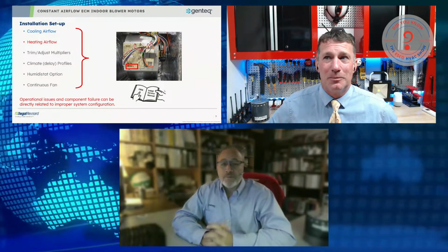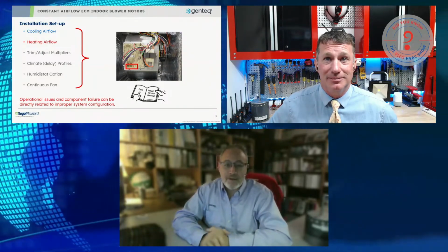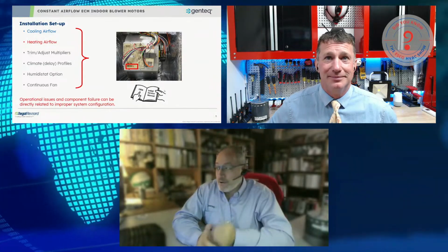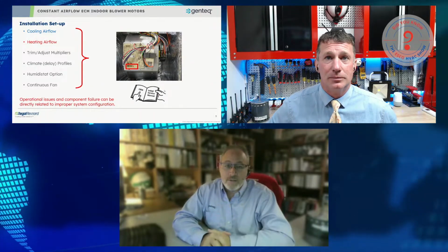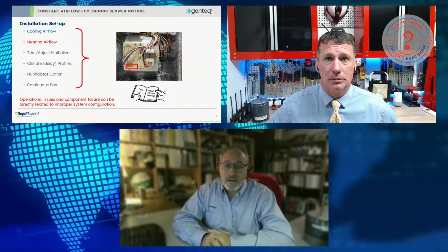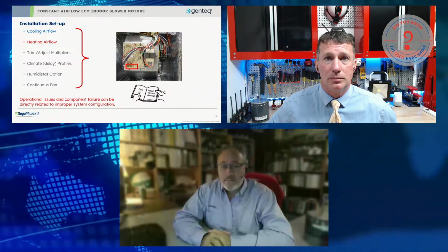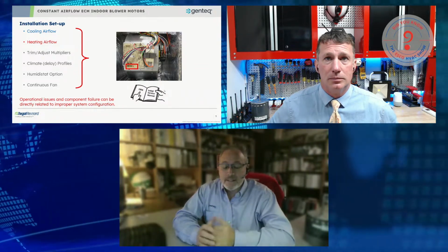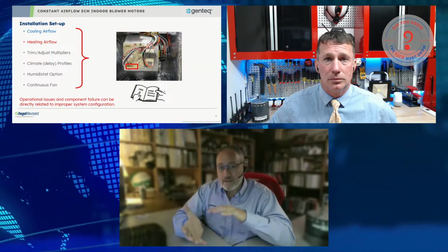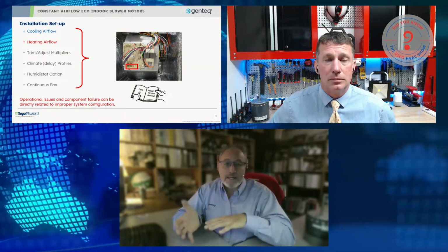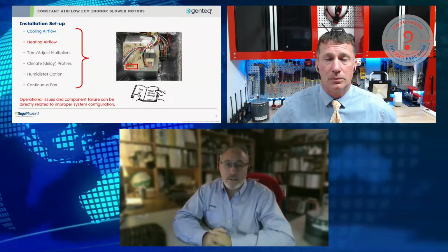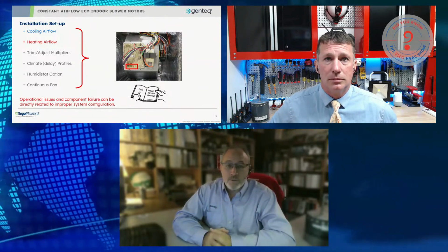And for those of you in Louisiana or other humid markets, you just laugh at us because that's your wintertime conditions, my peak summer. But there are truly some amazing features on these new systems that can adjust not only the amount of air, but the time that the airflow runs at certain levels to get more latent versus sensible removal out of the coil during a typical cooling call.